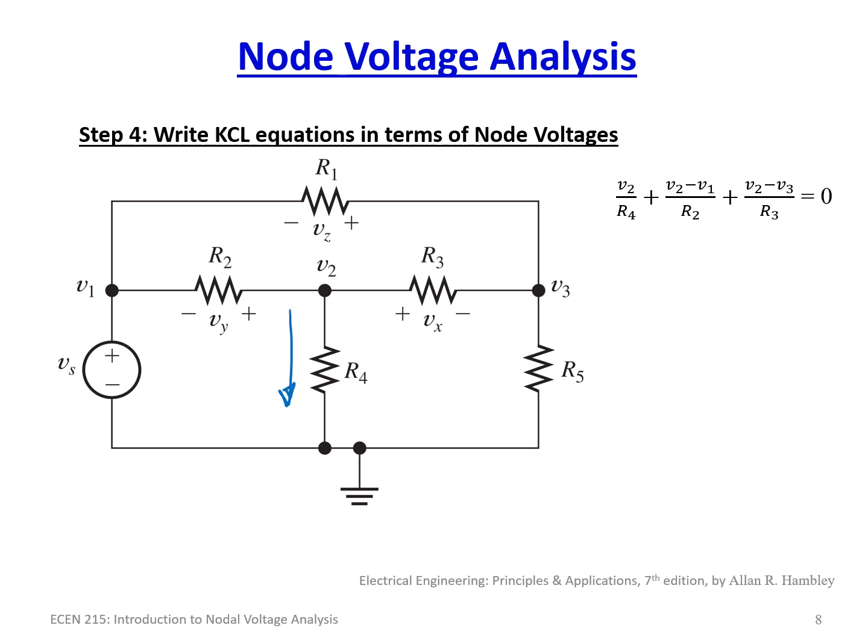So we're just going to assign currents. There are 3 possible currents for V2 because there's only 3 branches. We have the branch of current going this way, we have the branch of current going through R3 in this direction, and we've got the current going that way. So the V2 over R4 is that branch.